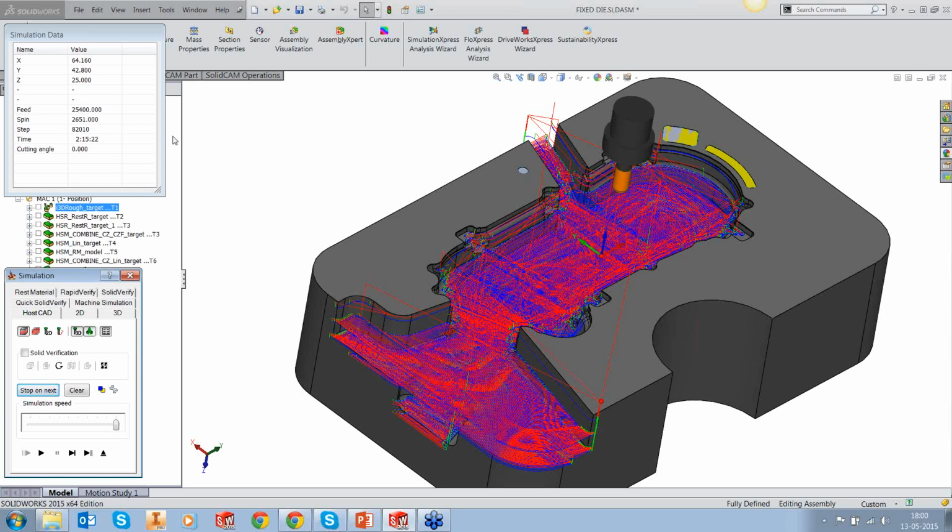So it's a decision that the user has to make depending on the size and the tool life of the particular tool that he's using. In our case, fortunately, we're getting a time of about 2 hours, 15 minutes, which is falling much inside the 180 minutes. So we're talking here of about 130 minutes. We are very much inside the tool life limit. So it's a great idea to do iMachining and scoop out maximum material.